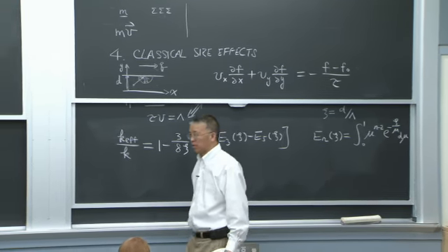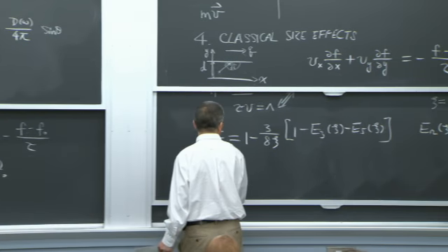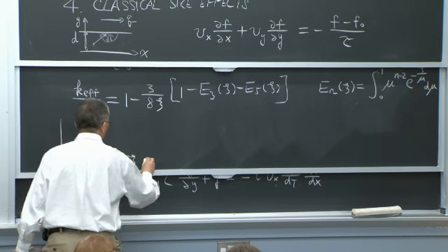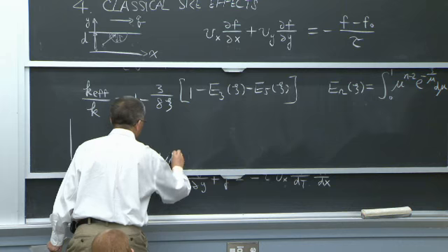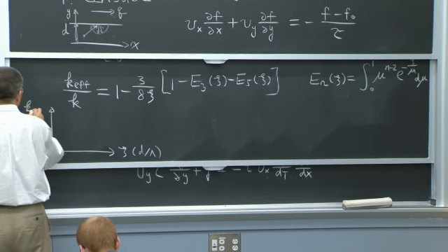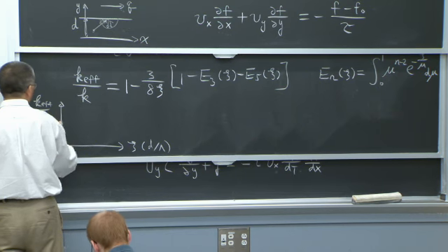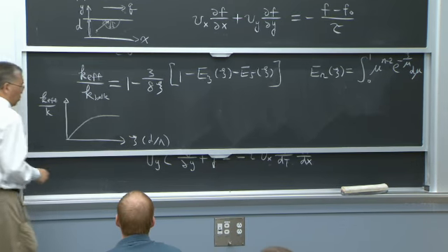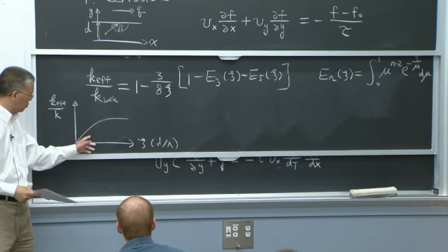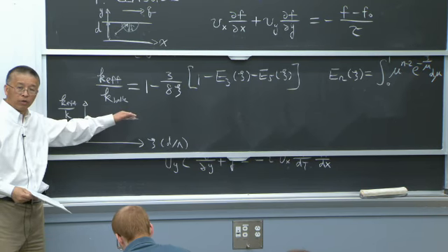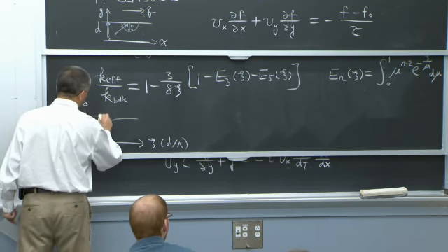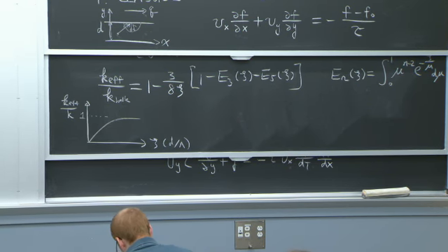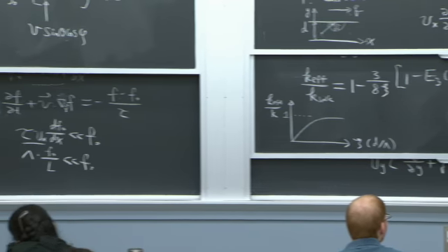Okay, so if you plot this effective thermal conductivity of materials, this is your K, say, d over mean free path, and this is normalized effective over K bulk. This transition happens at an order of 1. You approach the bulk thermal conductivity when the material is very thick compared to the mean free path. But when d is small, you have a deviation.